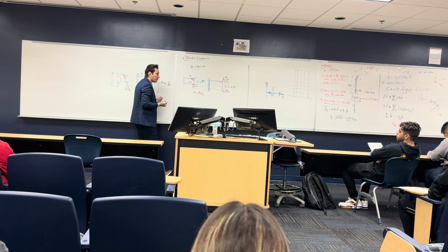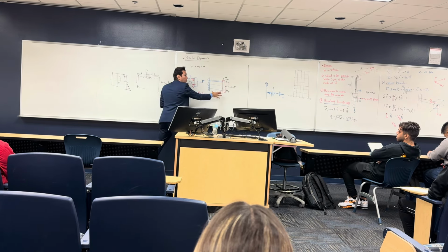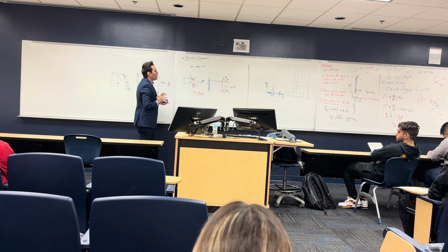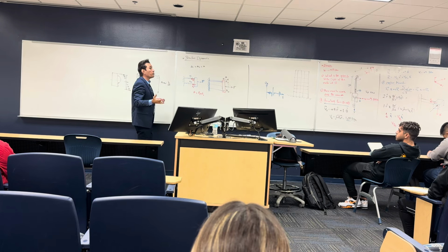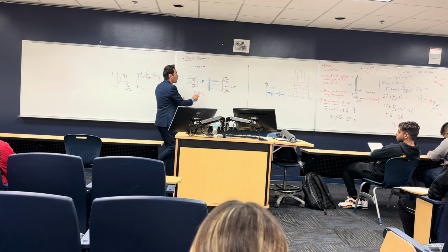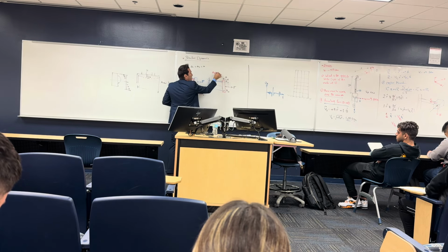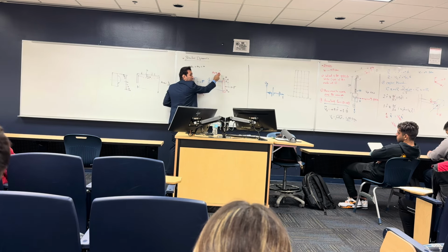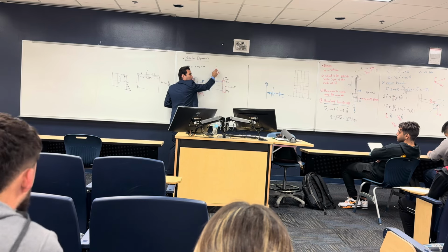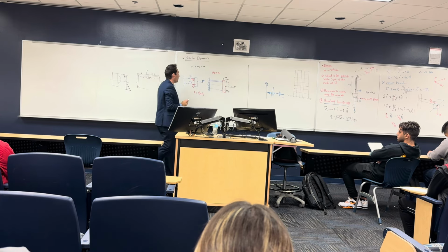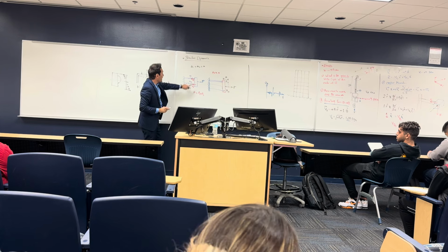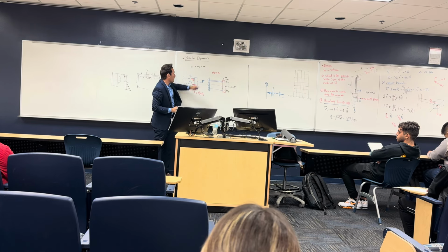The one that has more stiffness, right? The one with less stiffness is going to take less force because both have the same delta, and we know that the force P is equal to K multiplied by delta, right? Both of them have delta 1 and delta 2, so definitely the one with the higher stiffness is going to have a higher force.